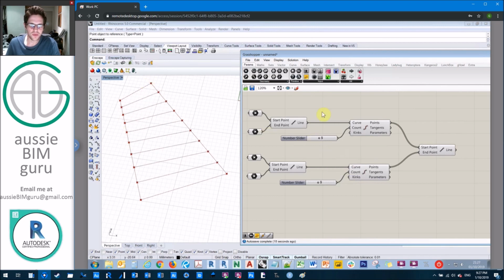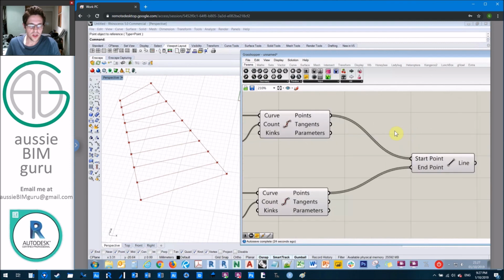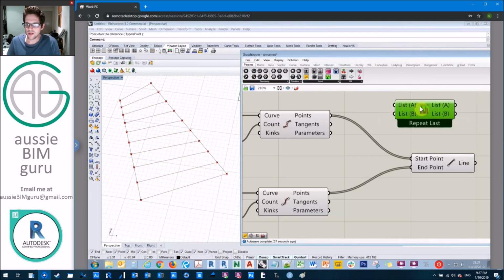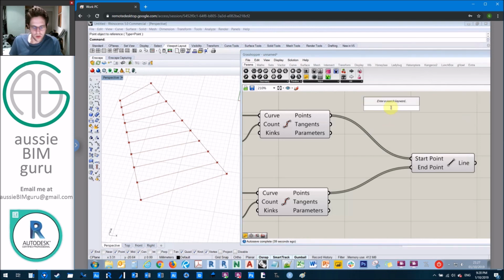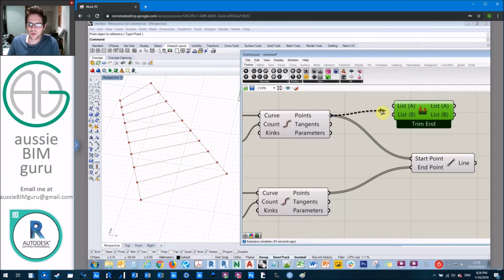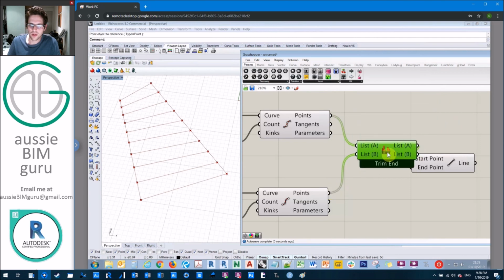So lacing is a little bit different in Grasshopper to how it works in Dynamo, which is good. The way it handles lacing is much more efficient than Dynamo, where you right click and specify the lacing per node. So there's actually functions for lacing. So we can say longest, and we can force a longest list, or we can get a shortest list. And a shortest list works differently. So the way that you work with lacing is you connect the 2 things you want to lace, and you use those as your outputs.